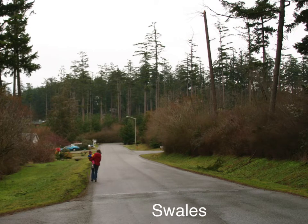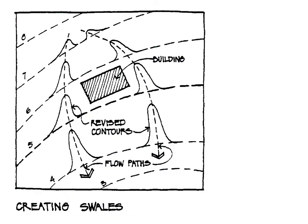Swales are what normal people call ditches. And here's looking along a street where you can see this. There's no subsurface pipe system, no stormwater system here. There's actually a series of swales on the side of the road, which channelize the water flow. It runs off the road and into the ditches and then is carried down and collected centrally. You will often use swales around a building.